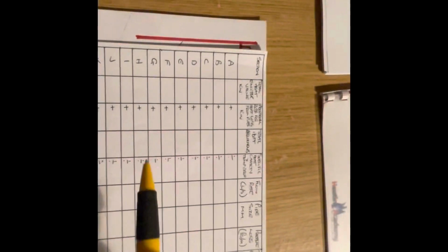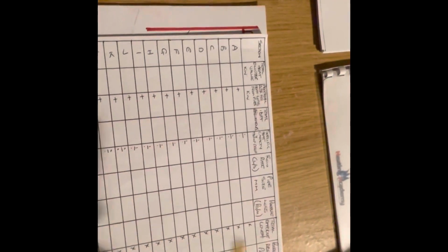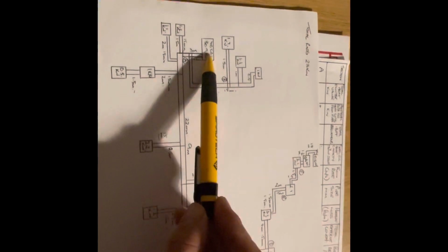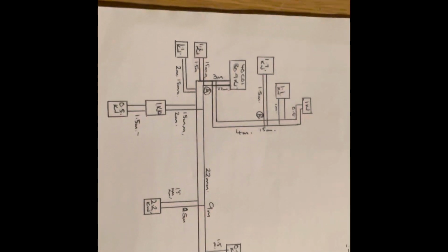I literally sat down and went through every part, worked out how many kilowatts was required, pipe work, pipe runs, and from that I generated the pressure loss across my system. When I worked out the pressure loss across here, and then added that to the boiler pressure loss, that exceeded what the pump could actually give me.